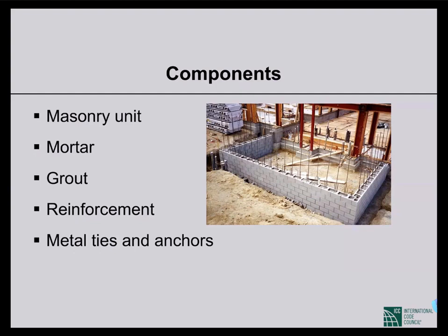Highly workable or almost flowable material. Then regular reinforcement is used with hollow bricks or hollow blocks. You can see in the picture on the right-hand side that vertical reinforcements are provided in the hollow cells of the hollow blocks, and those cells are filled with grout.